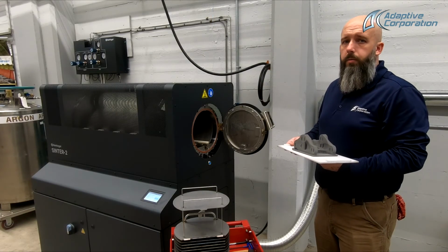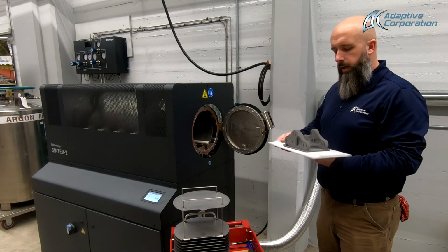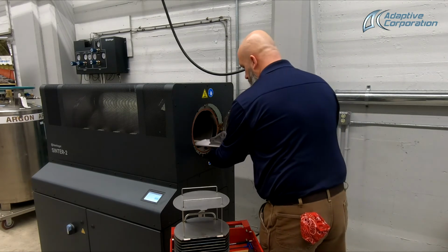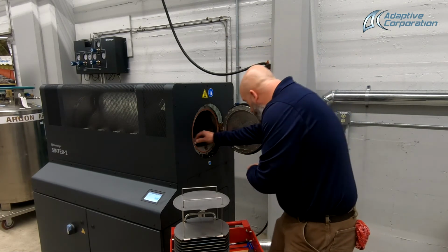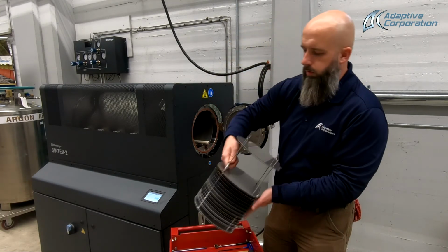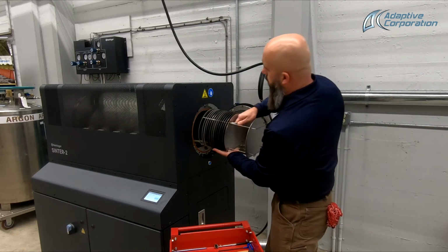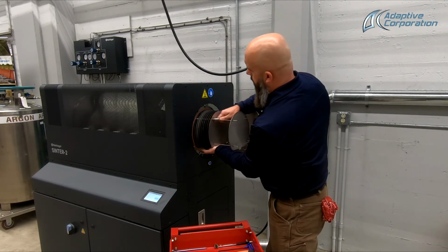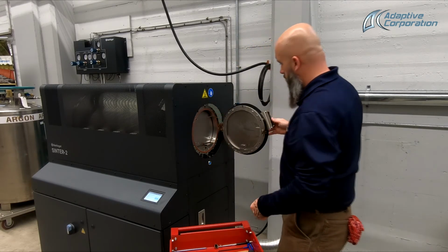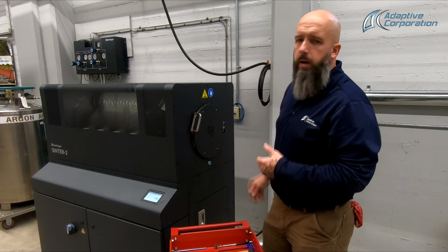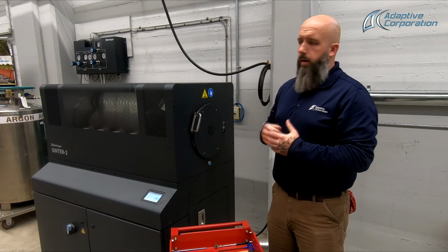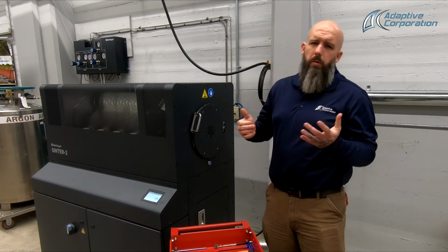All right, here we are at step 3, which is our Sinter 2. We can now process our brown part. Placing that all the way back into the Sinter 2, we'll put in place the final part here for safety. Okay, we can then follow the process with the screen of the Sinter 2, and this part usually takes around 30 hours.